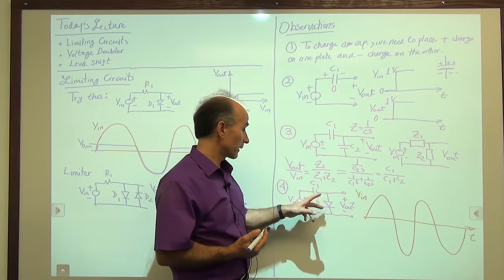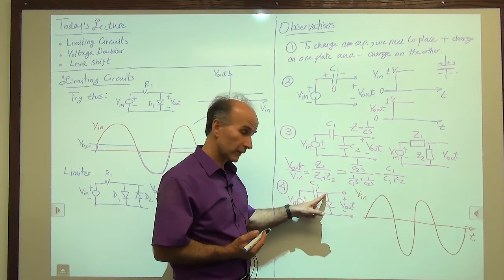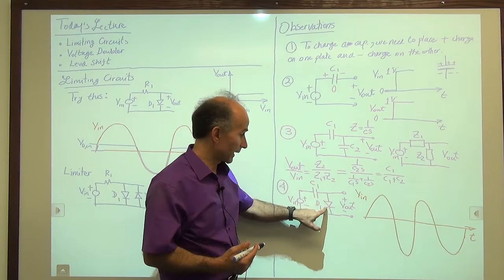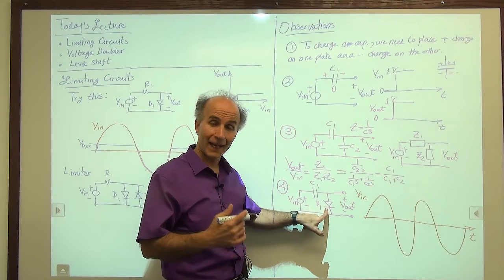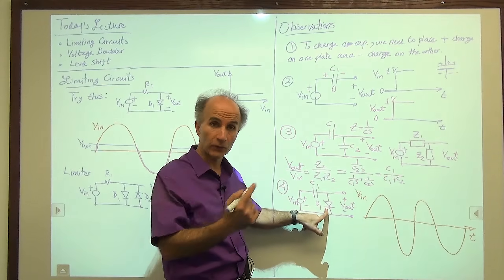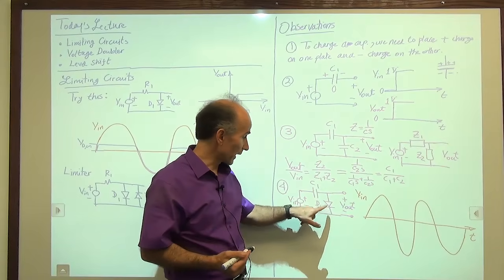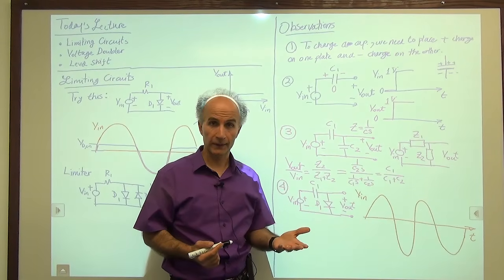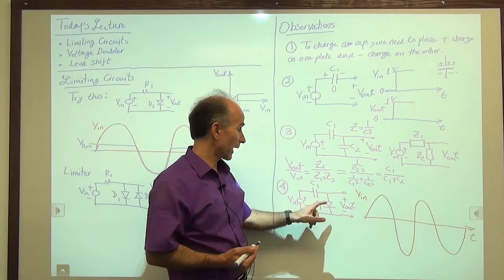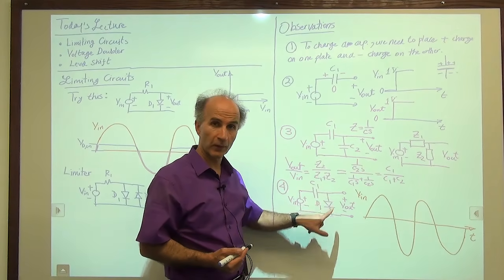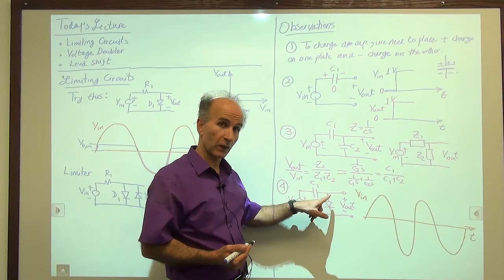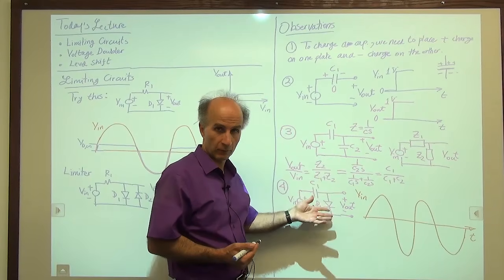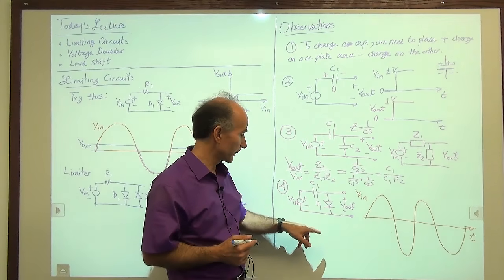All right? So because we started from 0, if this voltage goes up, it means it becomes more positive. But we know that an ideal diode does not allow anything other than 0 volt on it when it turns on. So as soon as this voltage wants to become positive, the diode turns on and becomes a short circuit. So the diode actually keeps this point at 0 volt with respect to here. If it were a constant voltage model, it would be not 0 volt, it would be 0.7 volts. But for now, for simplicity, that's what happens.